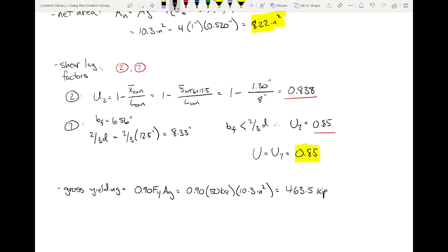Hold on. What I asked was, how much load are we putting on this tension member? 240 kips. How much are we designing it for? This number is how much usable capacity we can count on according to the gross section yielding limit state. Can it hold up more than this according to gross section yielding in real life? What is the capacity according to gross section yielding?